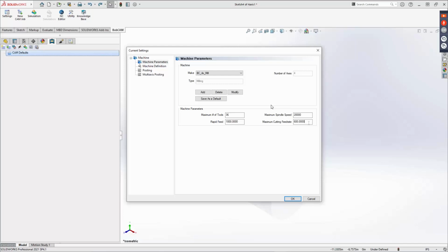Guys will say, hey, my spindle speed only goes up to 10,000. Well, it's right here, I can go 15,000. I put it in on the tool page, and when I post it out, it's coming out 10,000. Well, you want to put this up to maybe 30, 40,000. It doesn't really matter, because then you've got a buffer in there.